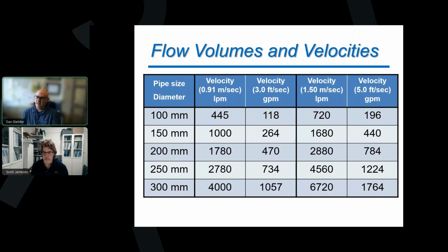Matthew asks, can you clarify what 600-meter flushing runs are? 600 meters from what exactly? From the distribution mains? Great comment. Yeah, that's what I'm talking about, 600 meters of length of pipe underground. So 600 meters up your distribution main. I know that might be a little bit long for a lot of your systems, but try and keep them a little bit shorter, that is always better.